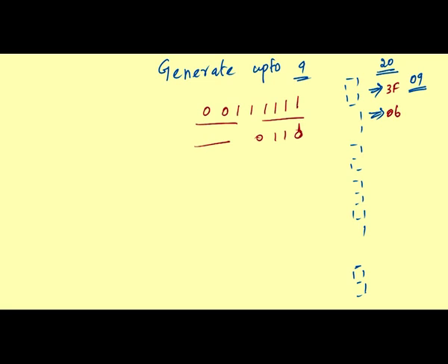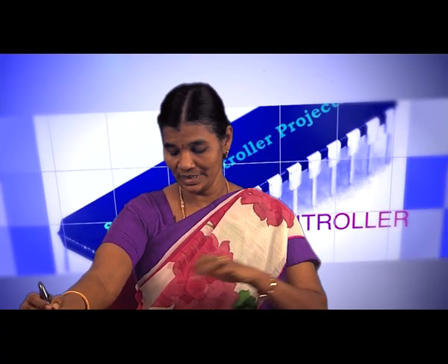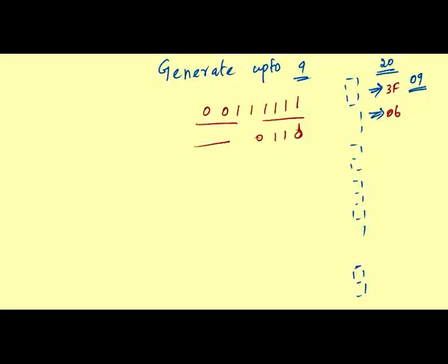Okay. The same thing we discussed in the previous program, you can initialize the memory starting address with 20, then the counter number as 09. So, you can use the same program; only here, instead of the earlier data, you give 0 to 9 with their corresponding hexa equivalents, and instead of 04 you give the number 9, because 9 text characters you want to move, right.